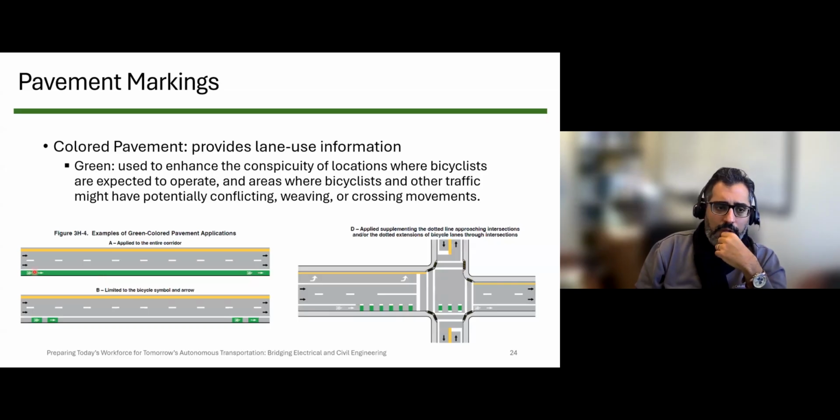on a bike lane. It could be a continuous, solid green applied. It could be just some arrows or symbols to show that this lane is for bicycles, and that would be in green, or it could be dashed green. But whatever it is, just remember that dashed is supposed to convey interruption. If you are using a dashed marking, for example, in this case, a dashed green marking, it is supposed to tell that here you should expect crossings to happen.